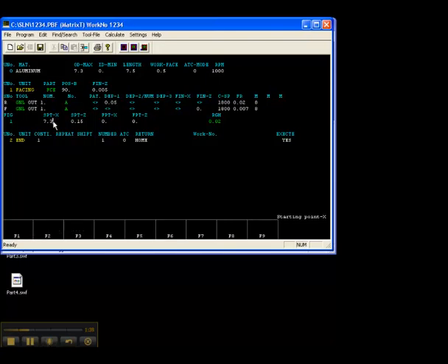And then you can see down here the shape lines. The starting X is the height of that line we constructed on the front face. The starting Z is the start point. When we originally set up the cut, we picked a starting point as if we were making a bar face. It looks at the Z position of that starting point to figure out where to begin this facing process. And then of course you can see the ending point is at 0, 0, and here's the finishing feed.